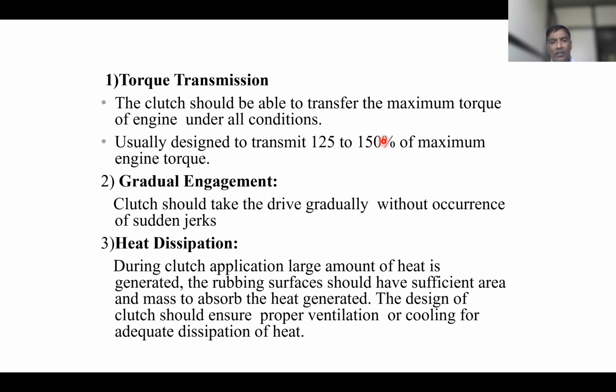While designing the clutch, it is designed to transmit 125 to 150% of maximum engine torque. So we are designing it to transmit more than the available torque, so that it will at least transmit the available torque at the driving shaft to the driven shaft.